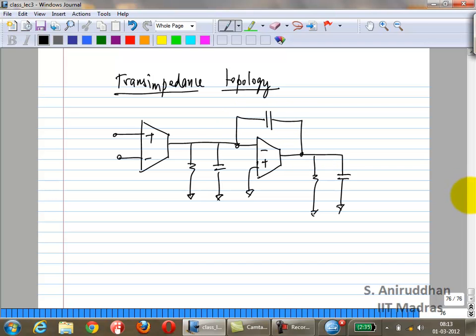So there is one thing we have not discussed with the single stage. So far, whenever we have looked at the single stage op amp, we have found that it cannot drive resistive loads, because it really kills the DC gain a lot. It's very good for driving capacitive loads, but very bad at driving resistive loads.